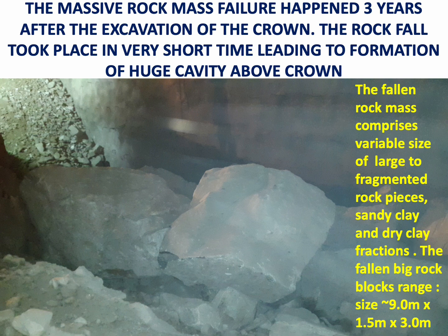For almost a full 3 years, the cavern, when it was being excavated through its height of around 58 meters, had reached a depth of 30 to 45 meter of excavation. Then in a very short time, the rockfall in its crown happened, which made a very huge cavity above the crown.